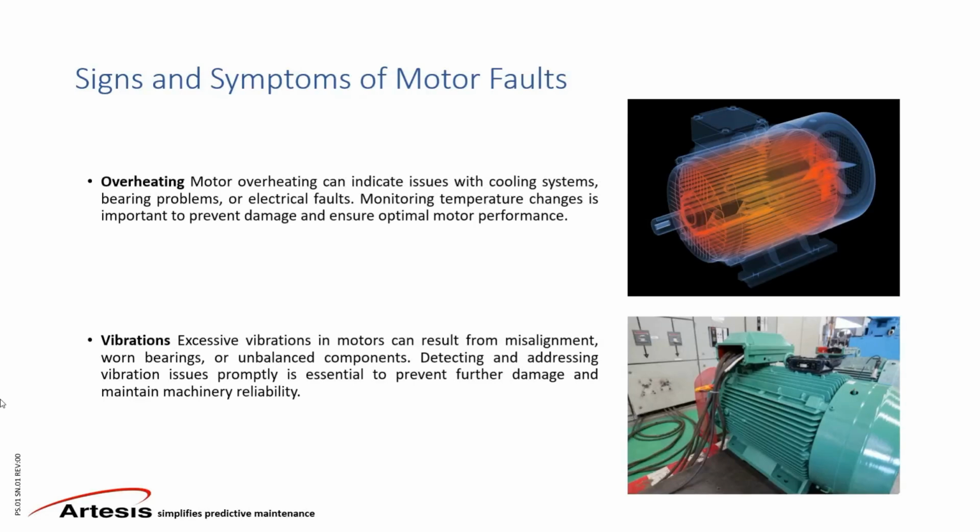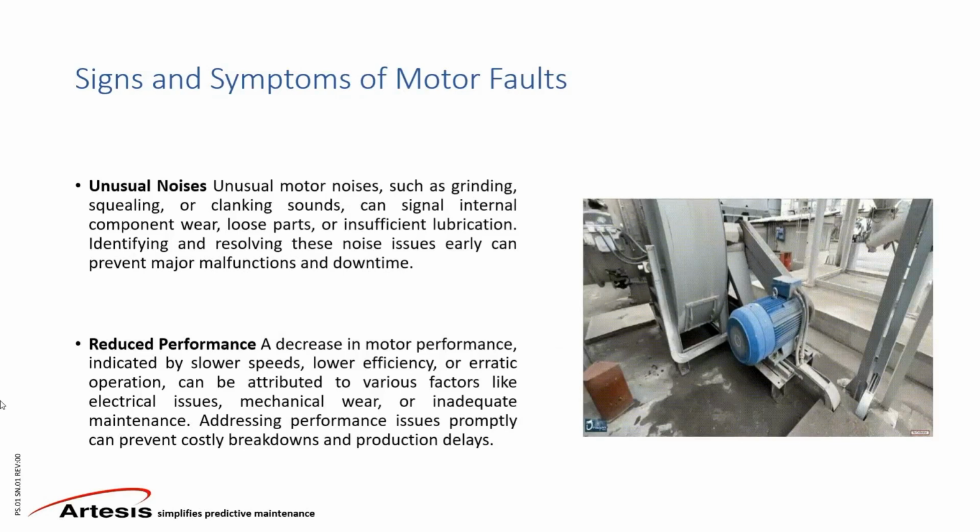And of course, the vibration can be detected with different technologies, and electrical signature analysis is, of course, one of them. And of course, if the situation is quite severe, you can actually hear noises. And of course, at that point of time, you actually are at the latest stage of the PF curve.